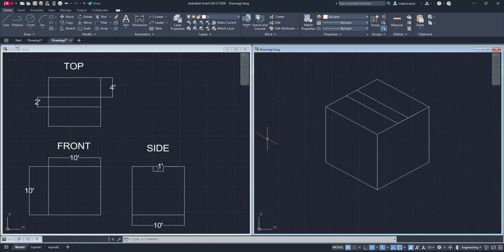What we're going to do next is take the line button again, and we're going to come down here. We're going to snap to this, and we're going to come down again, just 1 foot. That's all it is. It's 1 foot deep. We've come down there. We're going to come across 2 feet again to match this up. 2 feet. Then we're going to come up. We're going to snap to that. Escape. And now our channel is starting to look a little bit better.